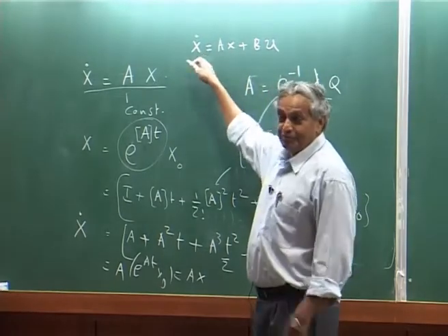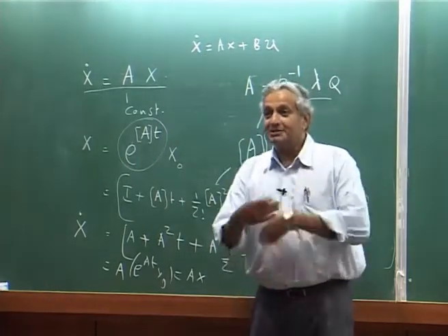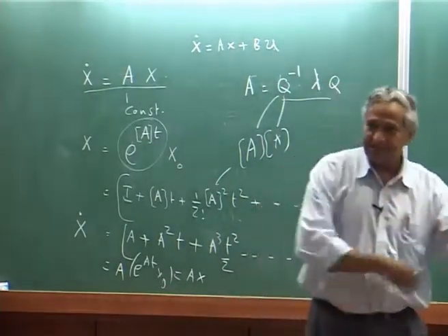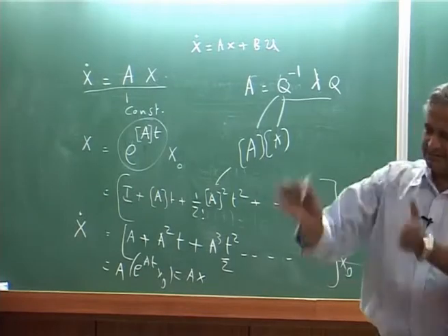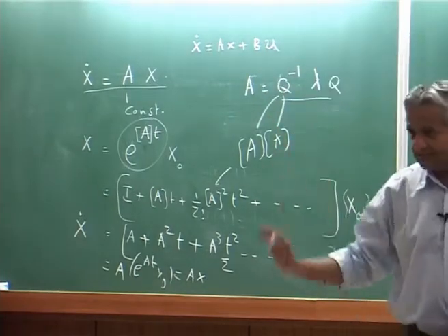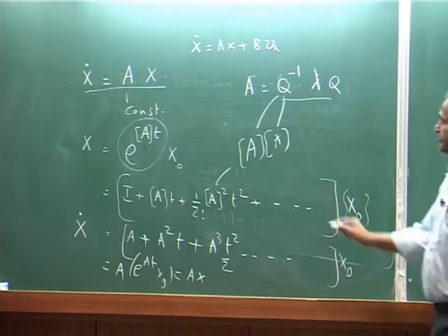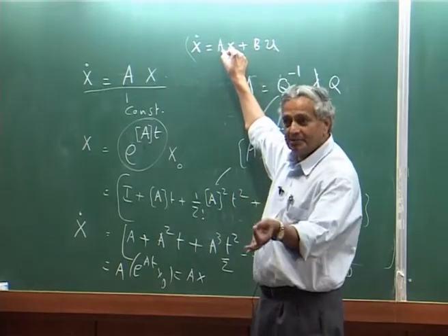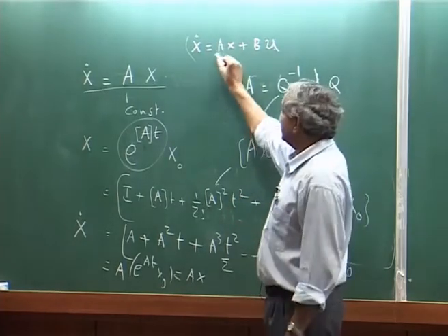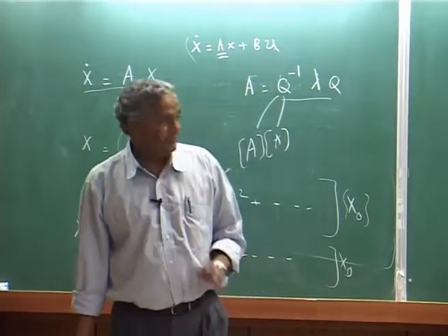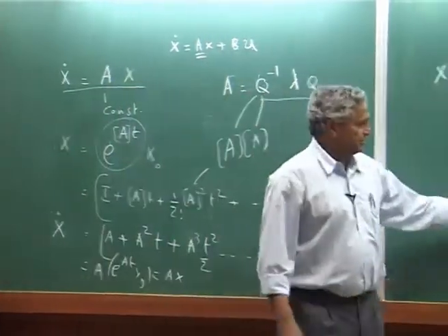Now, you say you want automatic stabilization, that means you have to give a feedback based on how the system is measured. That we will leave, we will not bother about the feedback control and other things. Just the basic system, this is the system. Whether the system is inherently stable or unstable is determined purely by the matrix A. Okay. Here we look for the eigenvalues.